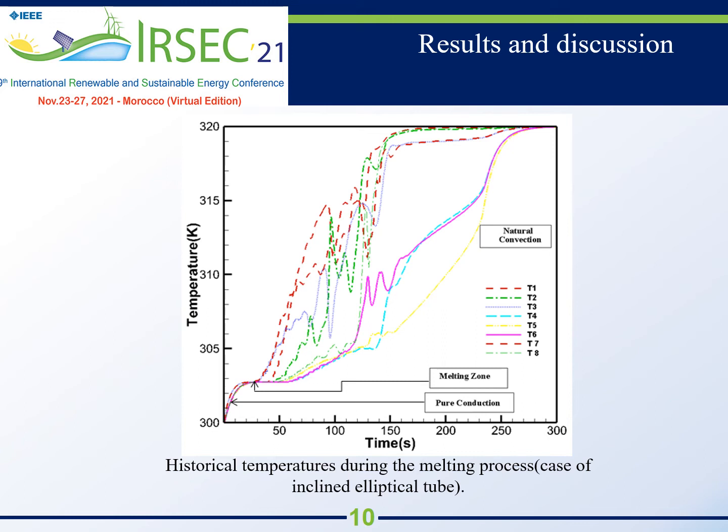This figure shows the temperature evolution of different thermocouples. At the beginning of the melting process, the temperature of all the thermocouples rises, keeping the same pace. Furthermore, the heat transfer mode that occurs is conduction. At the melting point, melting occurs so that the temperature graphs become horizontal. Temperatures continue to increase, but at a different pace in this stage.